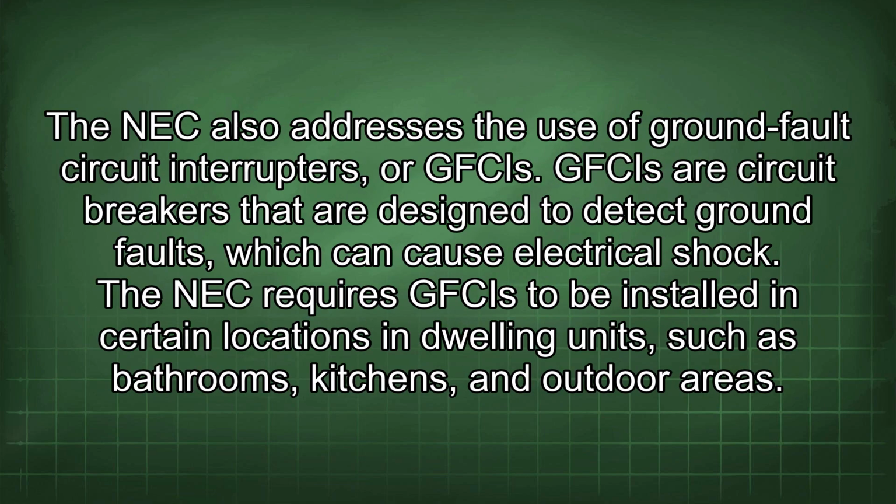The NEC also addresses the use of ground fault circuit interrupters, or GFCIs. GFCIs are circuit breakers that are designed to detect ground faults, which can cause electrical shock. The NEC requires GFCIs to be installed in certain locations in dwelling units, such as bathrooms, kitchens, and outdoor areas.